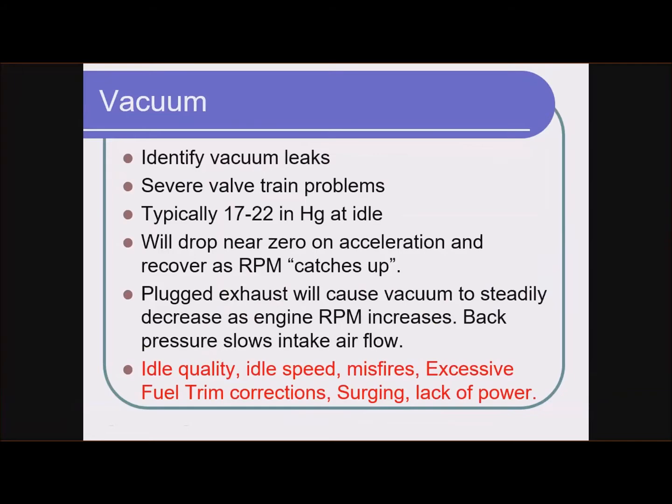That used to be really easy to do because a lot of things on the vehicle used to run on intake manifold vacuum. Now, as more and more devices become electrically controlled, it's getting harder and harder to find a vacuum port that you can plug a vacuum gauge onto. Typically still, the canister purge solenoid has a line going directly into the intake manifold. So on some vehicles, that's all you got. And that can be a pretty good sized line, so you're going to have some sort of an adapter for your vacuum gauge.